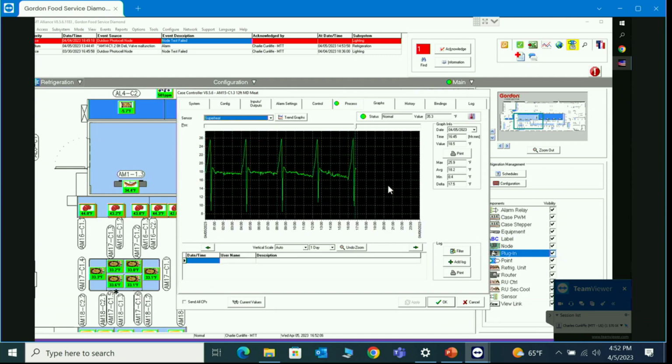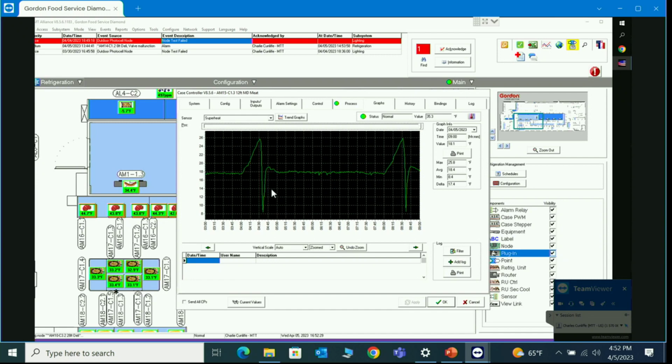Superheat is stable. The only time it changes is before or after defrost, but let me zoom in right here. Good question. I said it in the class yesterday. It was painful for me to learn as an old Sporlan guy because I was taught low temp should be 2 to 4 degrees of superheat, medium temp should be yada, yada, yada, right? With CO2, because it's temperature control with superheat backup, you're going to see much higher superheat. Because you're in medium temp cases satisfying with no APR. So you have to shut down. Right, I do all my modulation right through the EEV, okay?